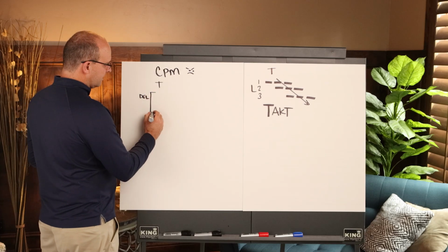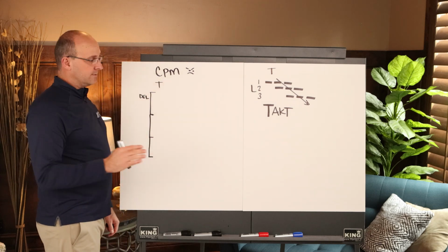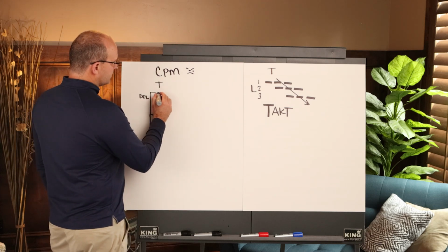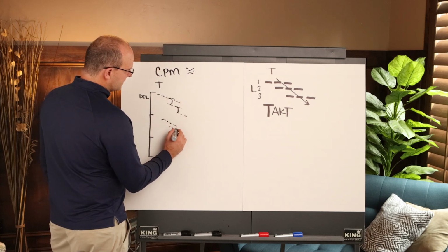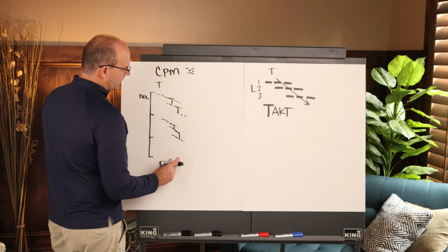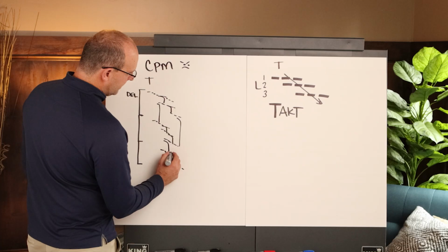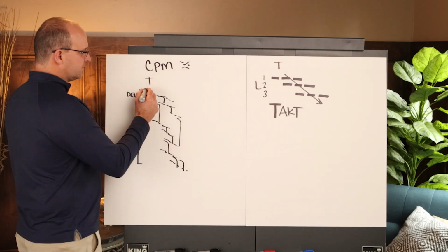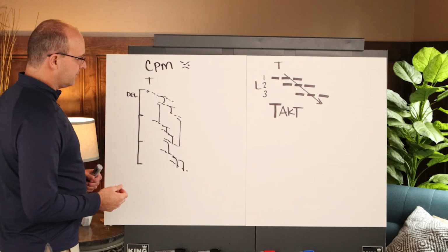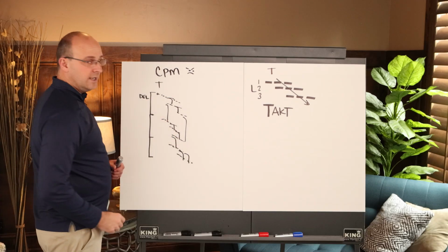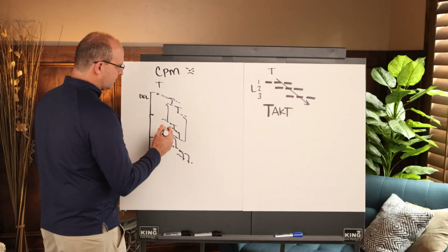So you will create a work breakdown structure, usually by deliverable, sometimes by location. The best people do it by location. But you'll start to create sequences here, and you'll logic tie them, okay? And what happens is your schedule gets so long that you as a human being forget what you did in here from a tie standpoint. The idea behind a CPM schedule is that it's supposed to logic tie all of these activities with a successor and a predecessor, and then calculate by going forward all the way to the end, and then coming back, calculate the longest path, which is your critical path.